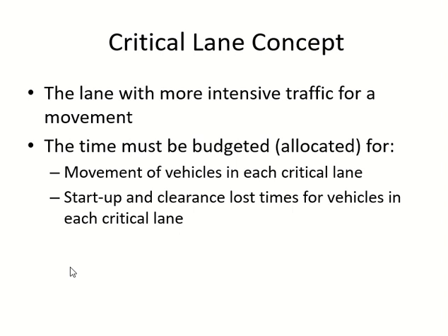One more point which I was looking for was the heavy vehicles. Even if the lanes are going in the same direction, heavy vehicles are supposed to be in one particular lane. So that lane, even with the lower number, because of the heavy vehicles, may need more time. So you should design for the lane which needs more time, because what can happen is you design for a lane which actually needs less time and the other lane is not satisfied. You have a long queue in that lane because you did not consider the slower lane.